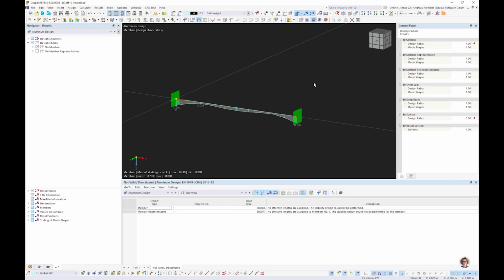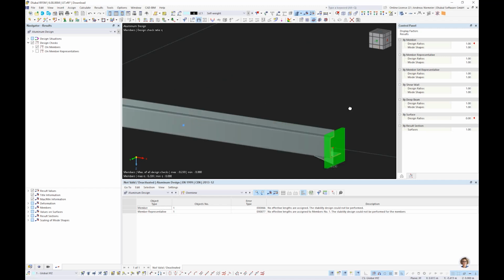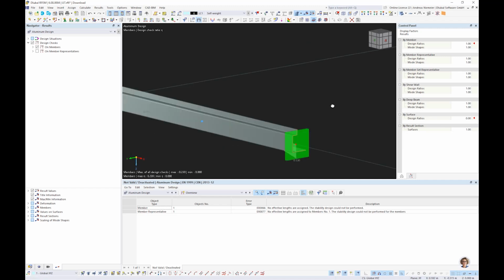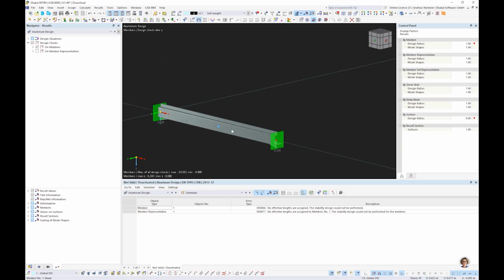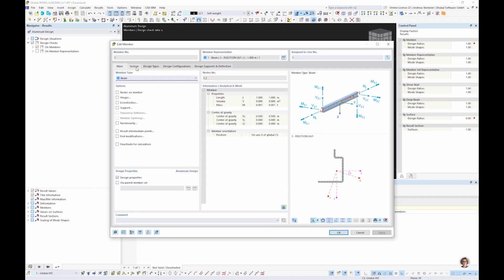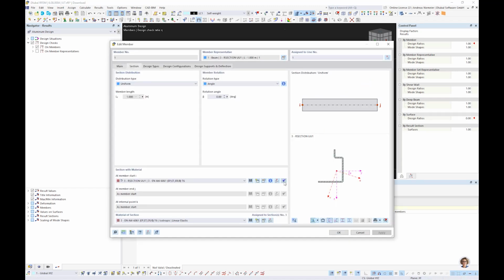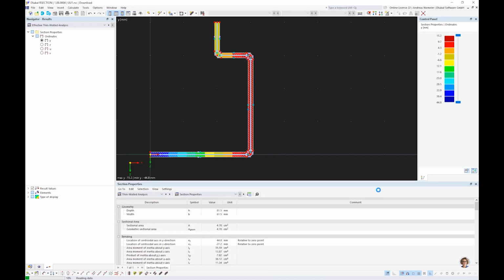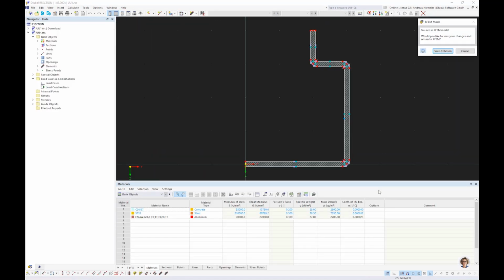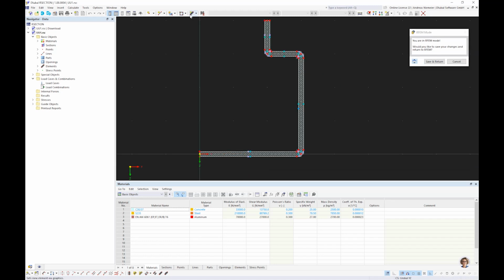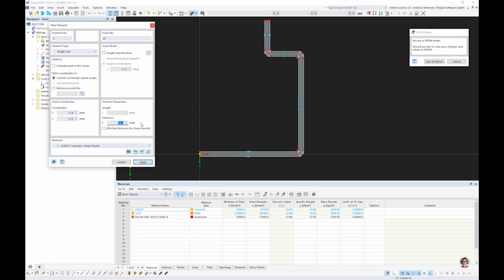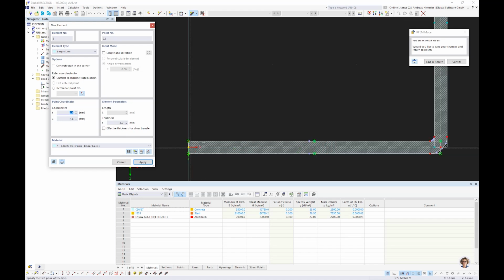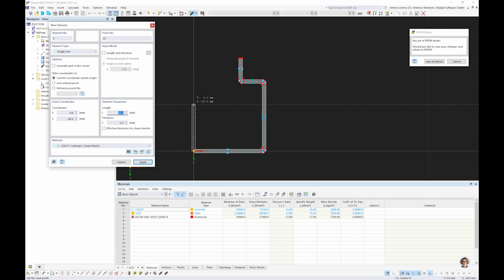If you realize you made an error, or you have a change, so the cross section changes a little bit, double click the member, and you have here an R section button, and this means the program opens the R section live inside RFEM in a special mode, and here you can say, I have a new stripe here because I forgot it, and you add it.